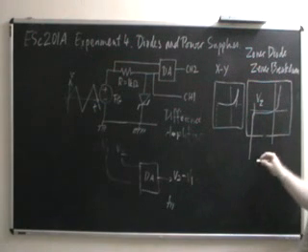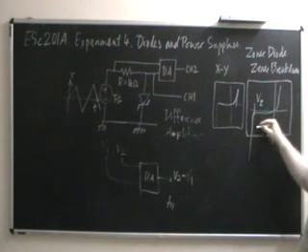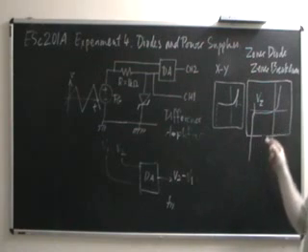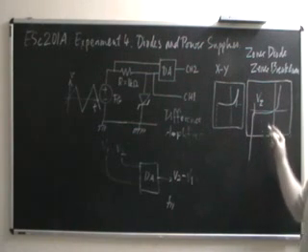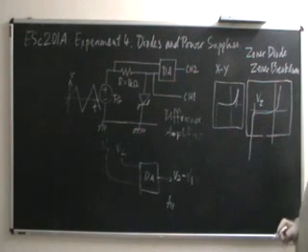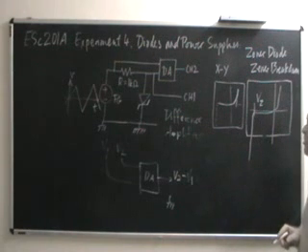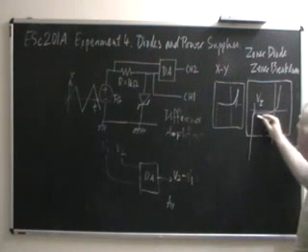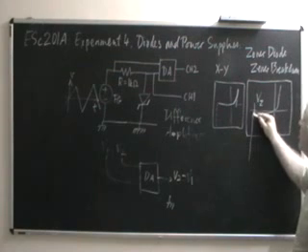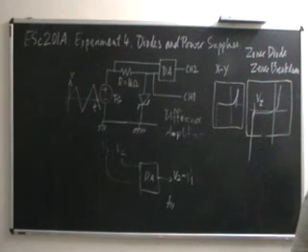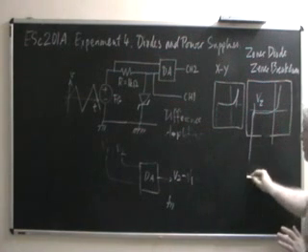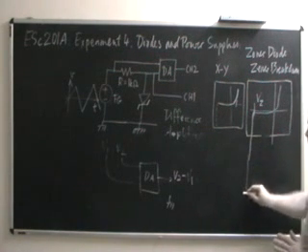You can even try to take the inverse of this slope and estimate the reverse resistance of the Zener under breakdown conditions. But the value will be so small that I doubt you will be able to get a very accurate figure. Initially it's slightly curved over here, but then it becomes literally straight. That doesn't mean that this curve goes on forever. There is a maximum current.